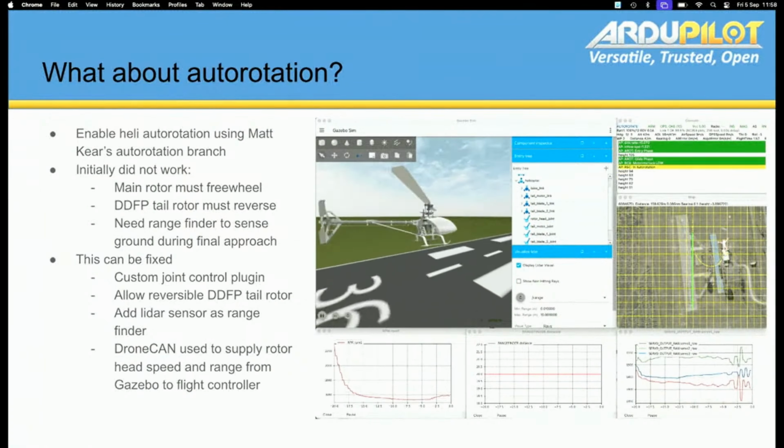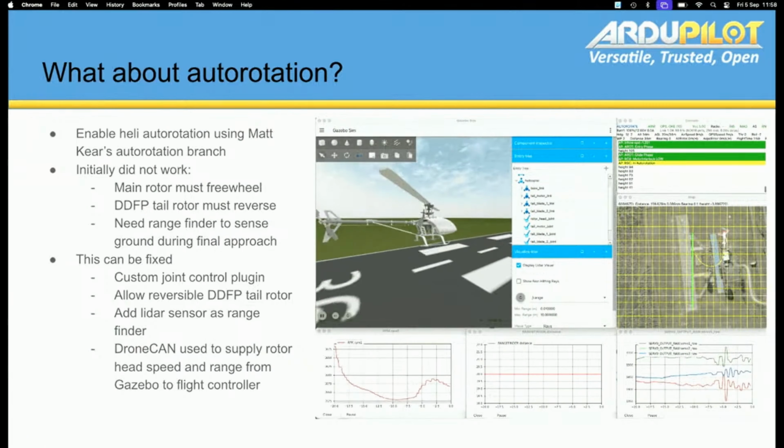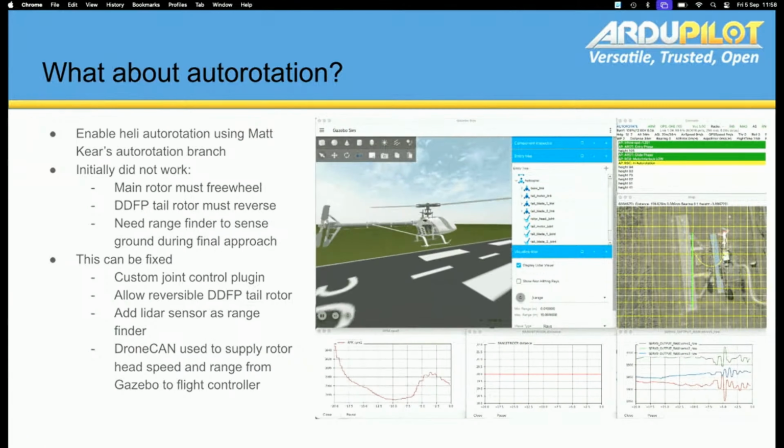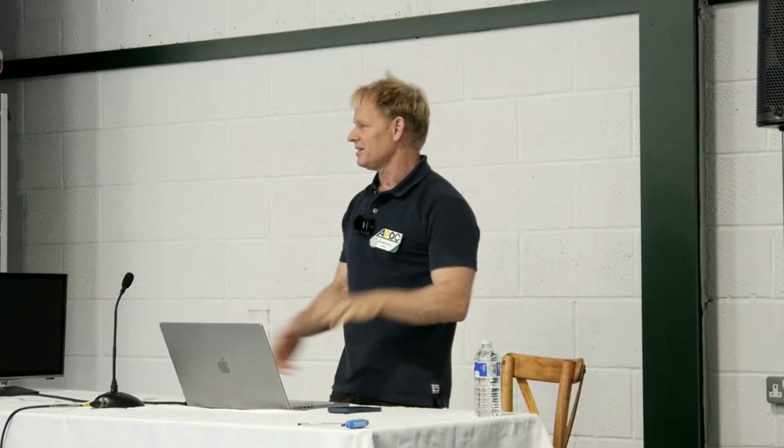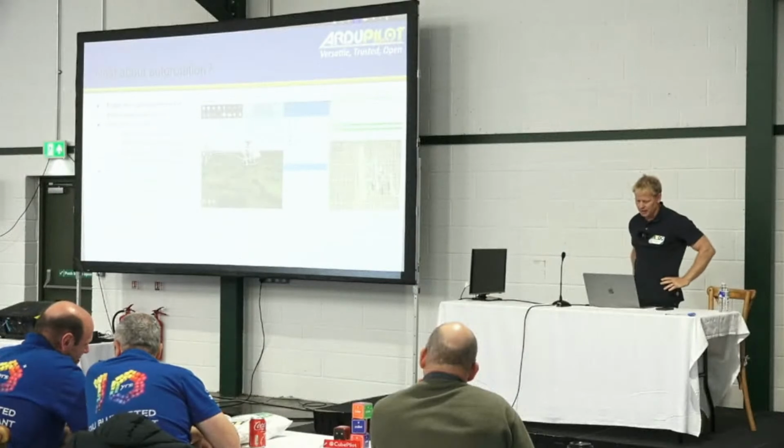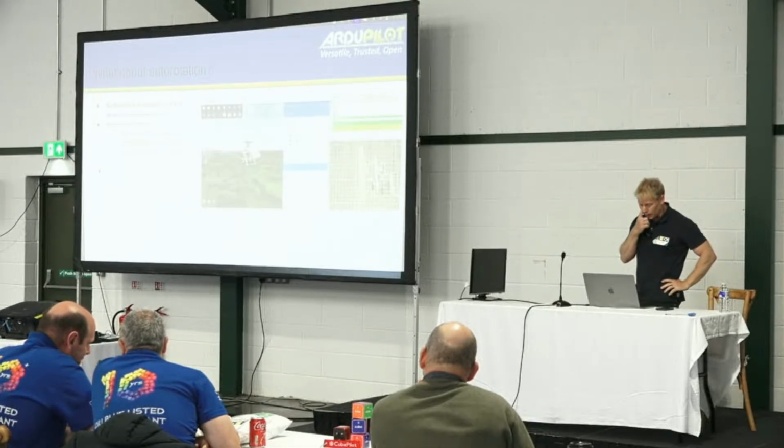And it auto-rotates. It's not perfect. It's still got some pitch control issues, but you put the helicopter up, you drop the main rotor power off, and you switch it into auto-rotate. It curves around onto its target auto-rotate flight path, wobbles its way down, and lands. So yeah, it works surprisingly well for a model that has the most basic lift and drag aerodynamics. I think we could do a lot better with it, but it's already doing quite a lot.